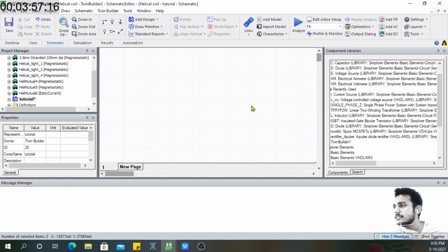So yeah, I guess I have already shown you the kind of circuit we are building. It will be a very simple circuit comprising a voltage source, and we'll define the frequency there. Let's say we can work around 1 megahertz or 6.78 megahertz. Let's take 6.78 megahertz for now, right? Then we'll put our model, the simulation of the coil that we did, somewhere in the middle, because it will transfer the power wirelessly.